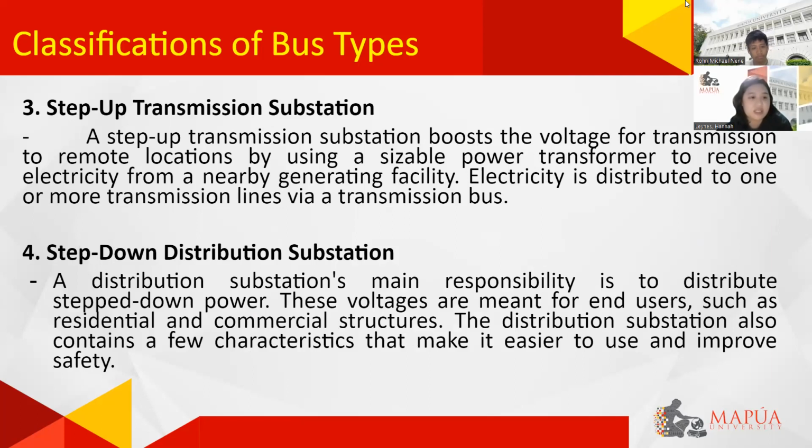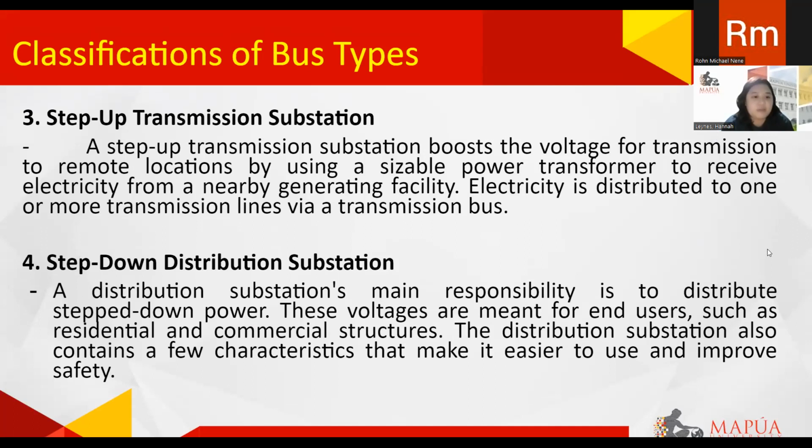So next is the step-up transmission substation. A step-up transmission substation boosts the voltage for transmission to remote locations by using a sizable power transformer to receive electricity from a nearby generating facility. Then electricity is distributed to one or more transmission lines via a transmission bus.